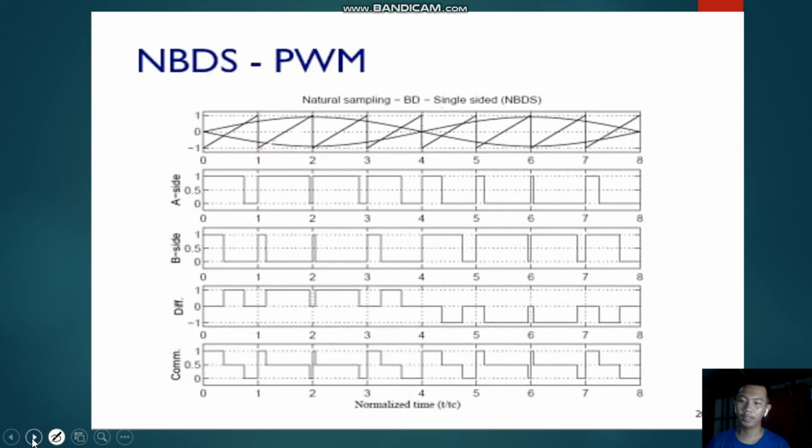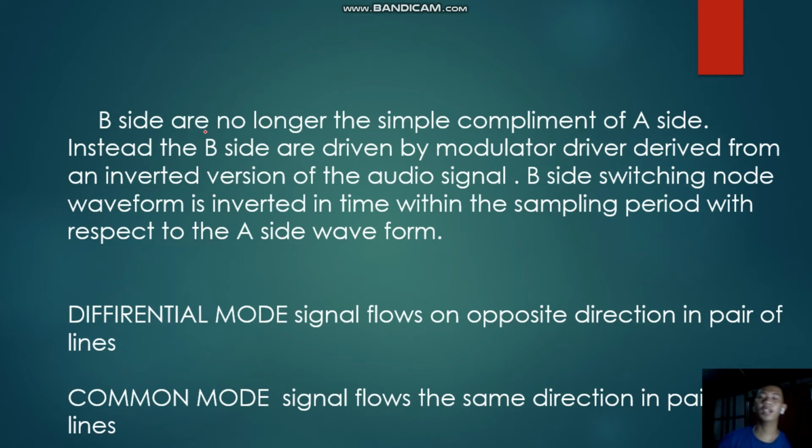So, differential. The B side is no longer the simple complement of the A side. Instead, the B side is driven by a modulator driver derived from an inverted version of the audio signal. The B side switching node waveform is inverted in time within the sampling period with respect to the A side waveform.